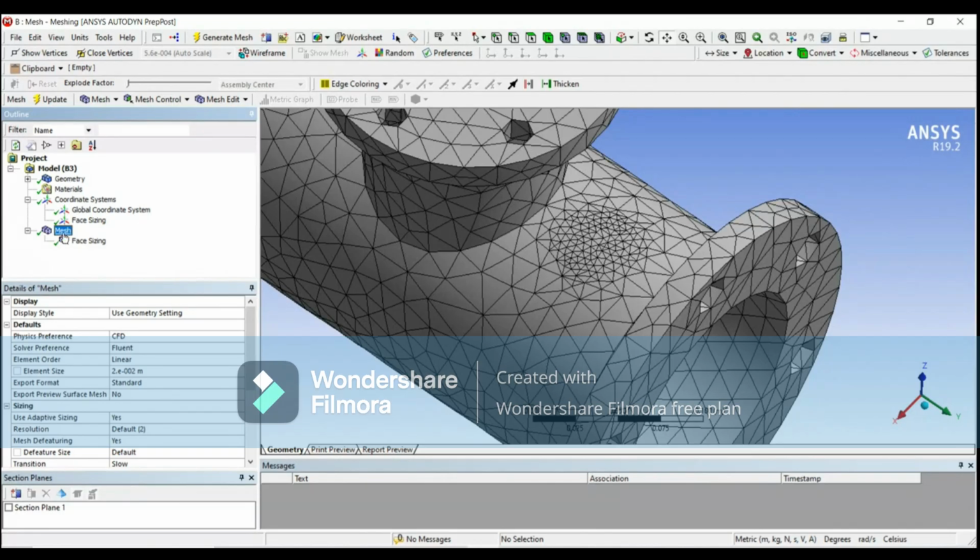Earlier, when the advanced size function was turned on, curvature and proximity, the algorithm got confused because it has to capture the curvature as well as do the fine mesh on that curvature. So whenever we are using advanced size function, the sphere of influence property does not work.